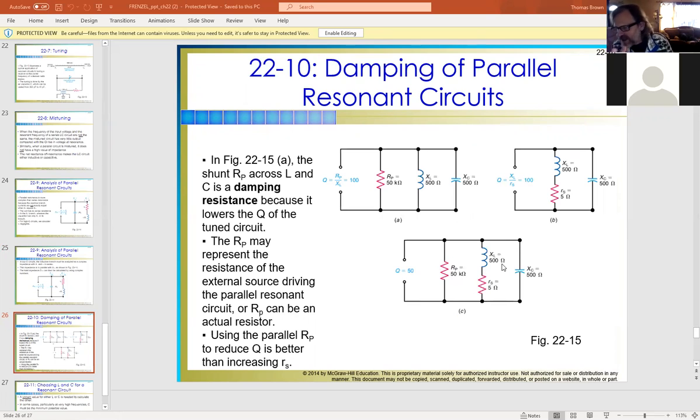And you'll notice this a lot of times. Well, because again, it's one thing dealing with the ideal world where it looks great on paper, but in reality, when you go and put it into effect, if you just have the inductor and the capacitor and no damping resistor involved, the circuit tends to be more erratic, if you will. It's more capable of flyaway, more capable of distortion.